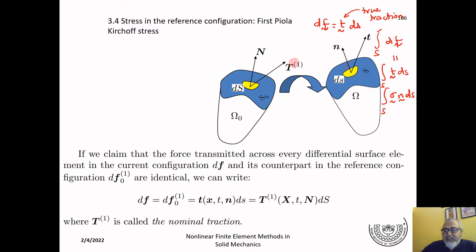What is the traction that I would have on this small area? Whatever this traction may be, by Cauchy principle, I must be able to connect the traction to the normal through a stress-like quantity. Therefore, if the traction I say is T1, I should be able to write it is equal to n times some quantity P, where P is a stress-like quantity.